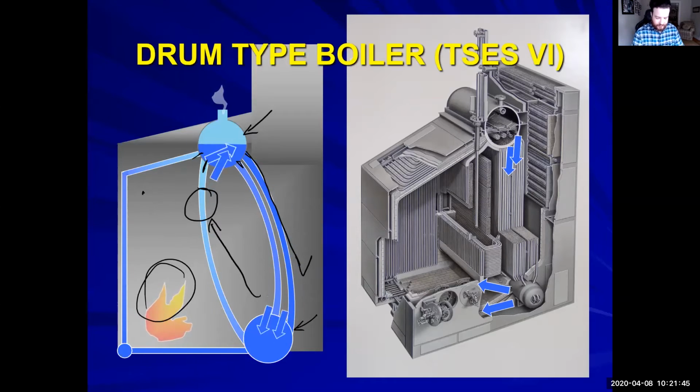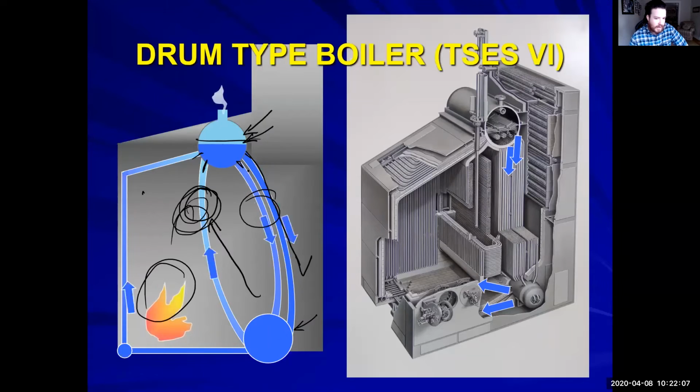But what is happening? So if we're generating steam, what's keeping our water level in our steam drum? What's keeping it at half? If this side is creating steam and all these tubes are generating tubes, what's going on? How can we have a steam drum that's half filled with water and yet we are producing steam on this side? How is steam holding up a column of water? The water in the steam is condensing. So what happens to that energy?